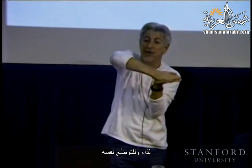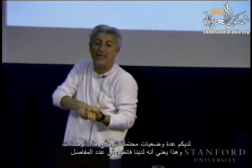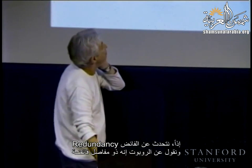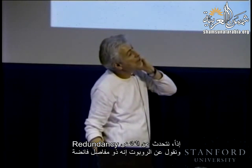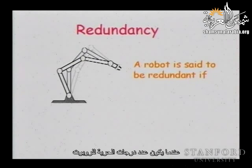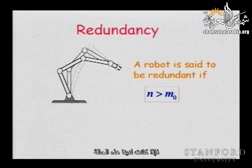So for the same end effector configuration, you have different possible configurations of the structure, of the links. And that means we have redundancy. So we talk about redundancy, and we call the robot redundant if the number of degrees of freedom of the robot, n, is greater than the number of degrees of freedom of the end effector, m0. So if we have this situation, m0 here is equal to 3 and n equal to 4, then the robot is said to be redundant.